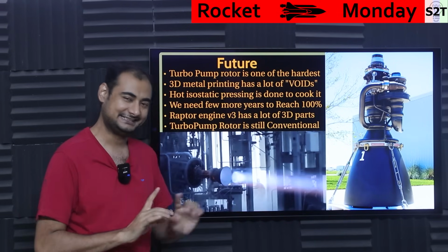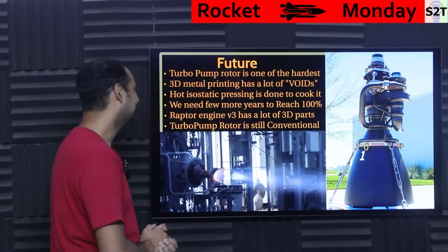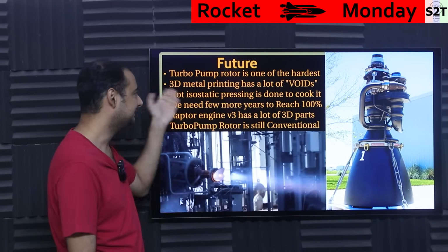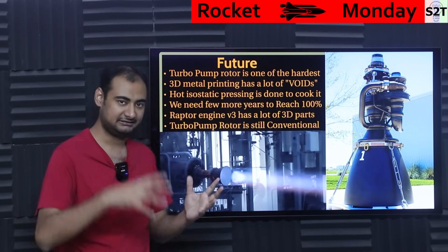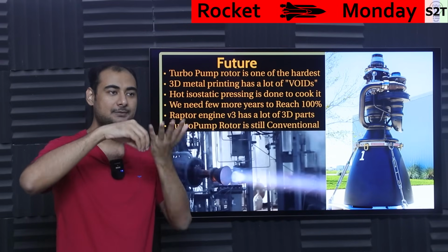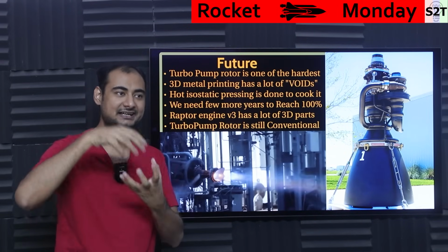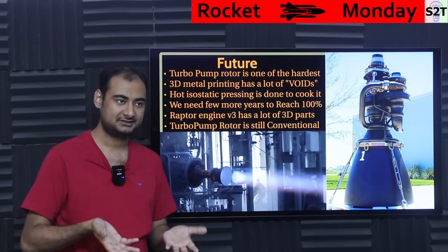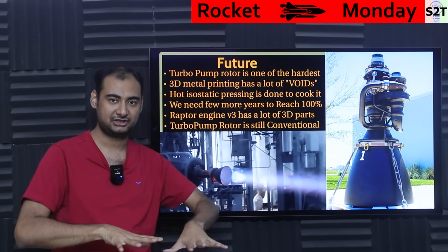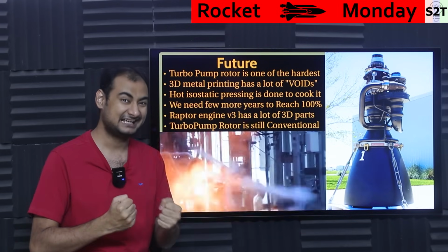Turbo shaft, it's like, yeah, no. Turbo shaft is like, no. And why is that a problem? The problem is 3D printing fundamentally creates a lot of void. So when NASA is testing it, and if you look into an electron microscope, you will see powder that has been melted. So fundamentally, it's not as robust as a forged part. Forged part would be the go-to here, and second would be liquid casting. So you have liquid metal pouring, gravity is shaking it down, and you shake it, gases move up and all that. So that gives you a very dense part.